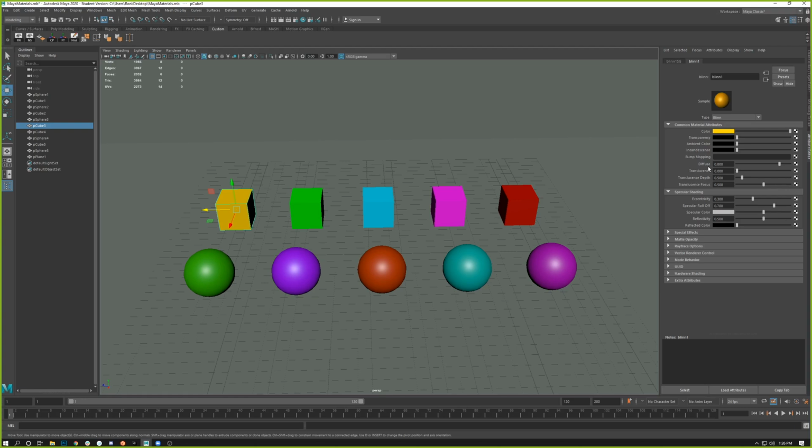Think of some red cars that you might see, like a really nice red car. It looks really red in noonday sun, but as soon as you get later at night, it begins to lose its color quite fast. Metal tends to have a low diffuse. It tends not to keep its color the darker it gets in the lighting situation. The default is set to 0.8. What you're supposed to do is try to judge your scene when you make materials as if everything's being made in the noonday sun, and then adjust from there. So you just have to think a little further.